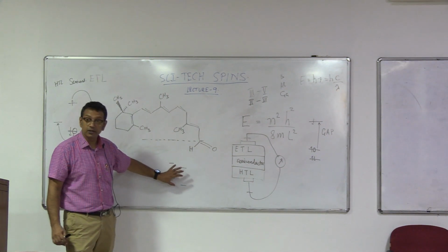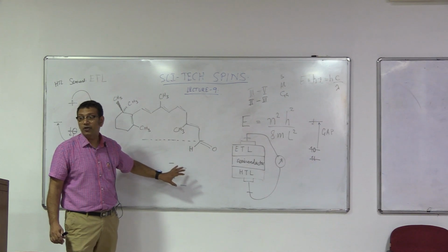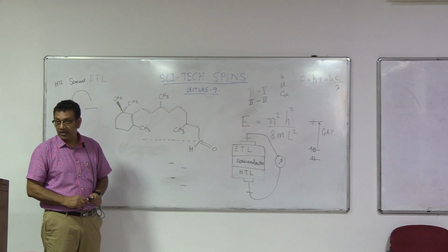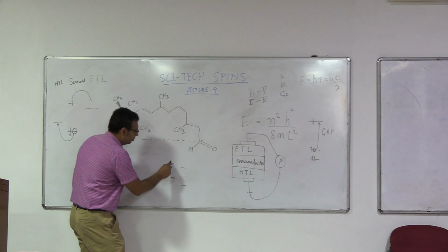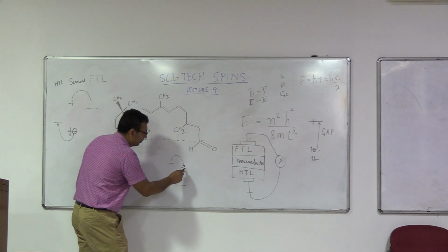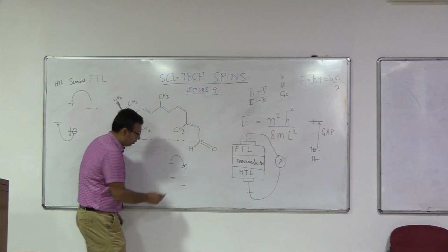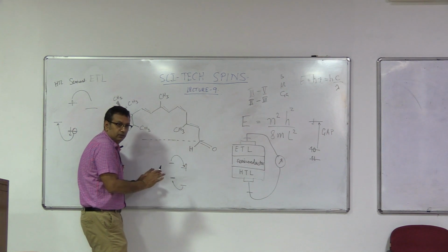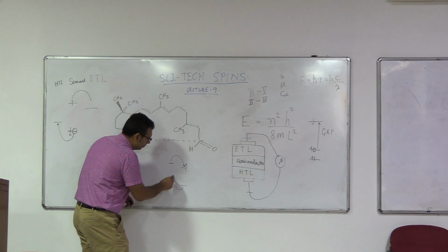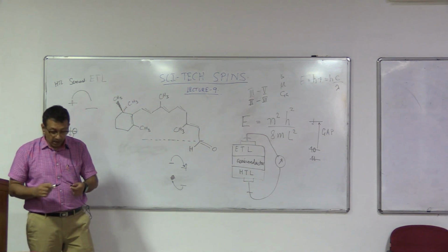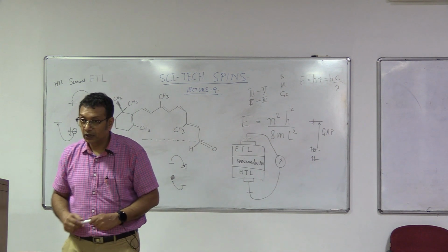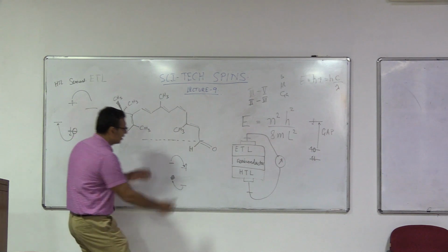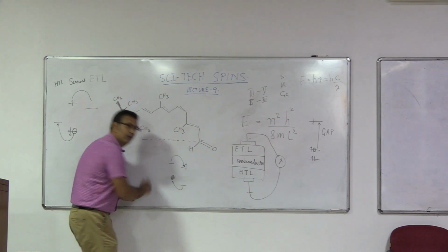Heterostructure materials. The moment you make this heterostructured material, you ensure that after excitation with light, the electron would immediately be found here, and the hole, because this is a lower energy for the hole, even if it was there, it would be always here. You have a natural charge separation. At the moment you have your natural charge separation, now I can put my ETL over here and the HTL over here.